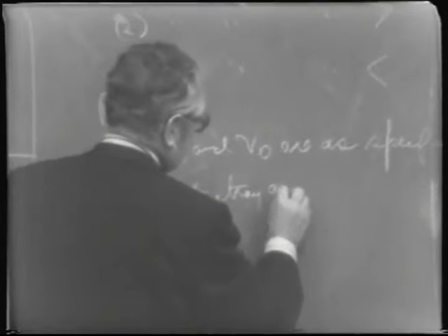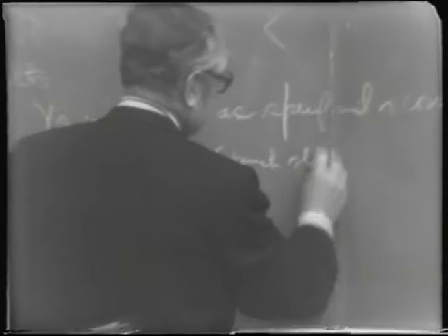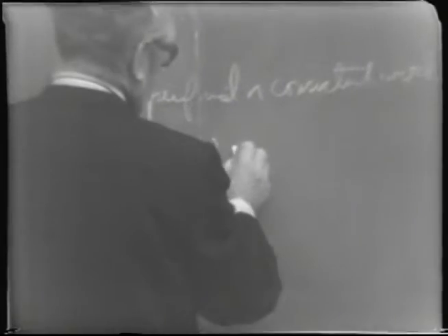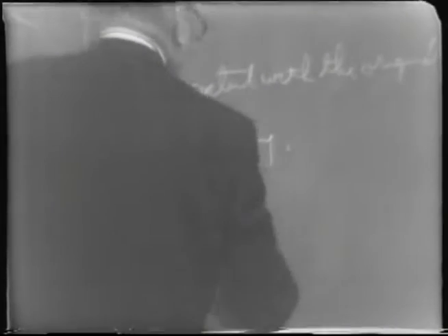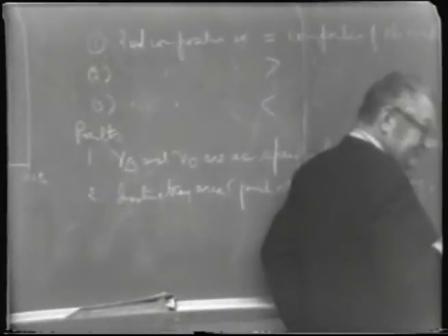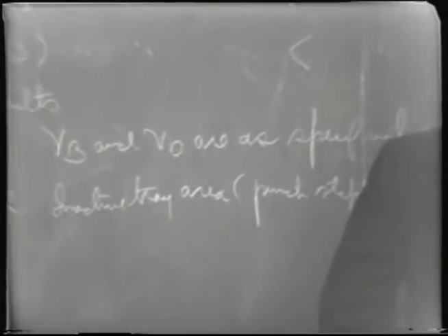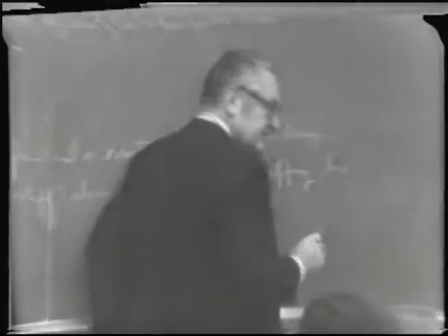Situation 2, we have an inactive tray area, a series of pinch steps above the feed tray. And also somewhat better stripping, if you want to put it that way, say improved stripping, but lower product quality or lower product concentration.